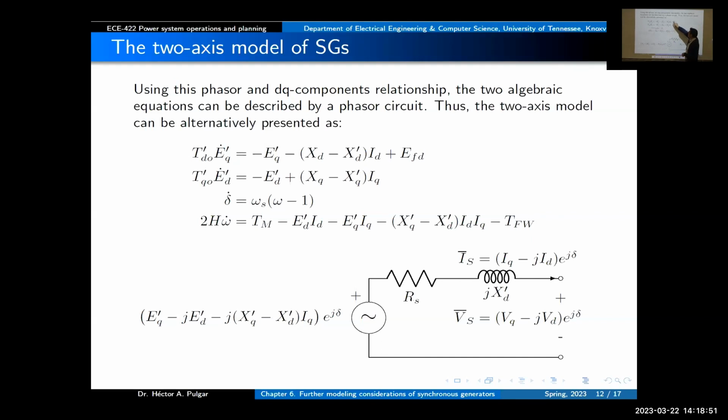That's something that we can control by controlling the DC current in the field winding. But when you do that, you will also have some impact on this other component that is related to the Y1Q damper. So again, with this known, when we make this derivative equal to 0, as you can see here, this is known.